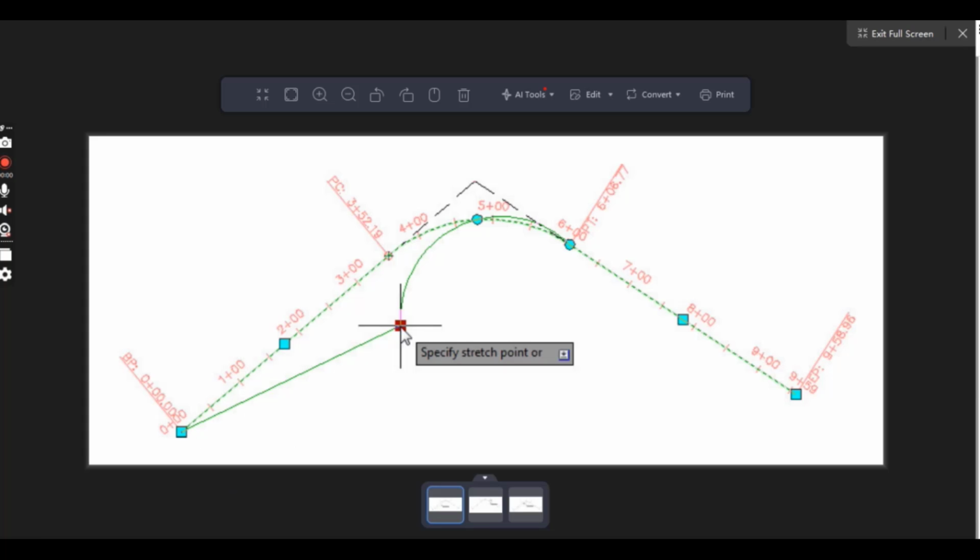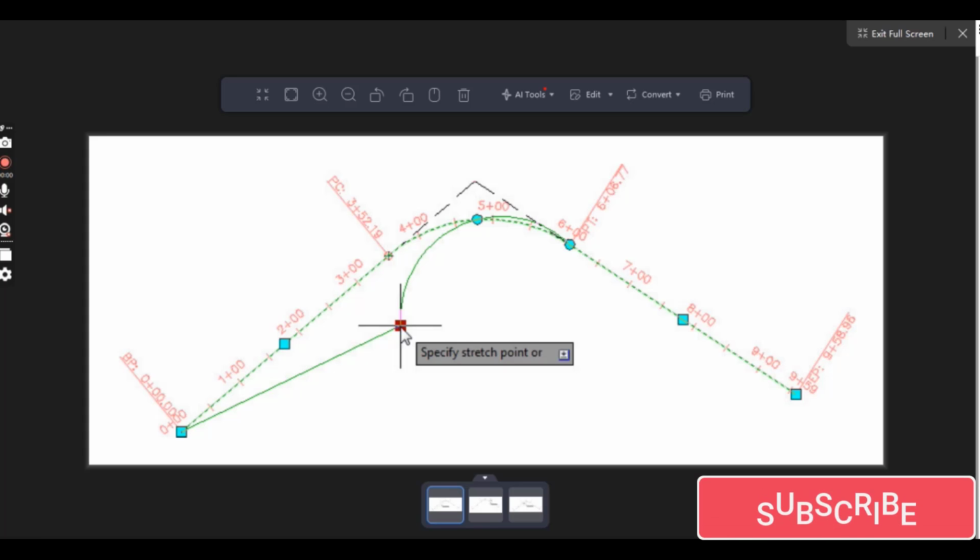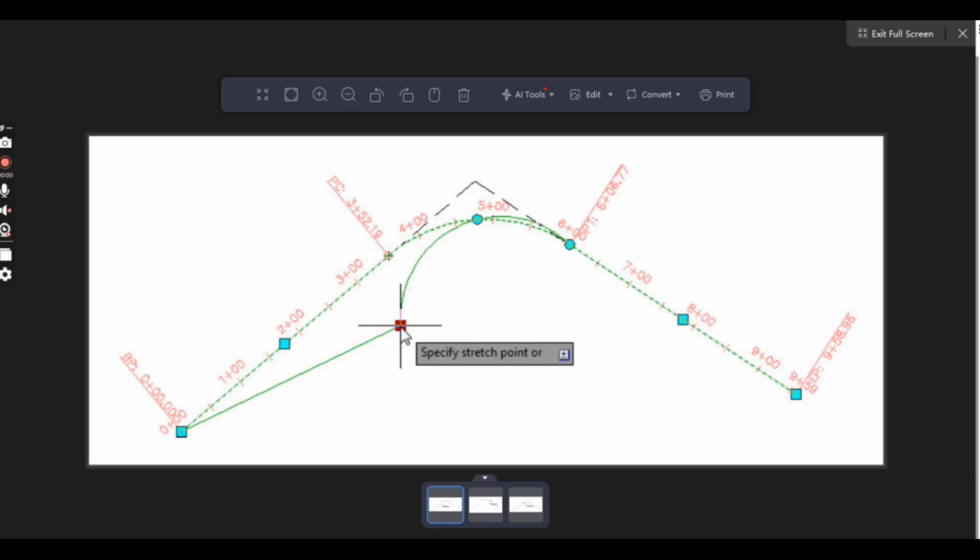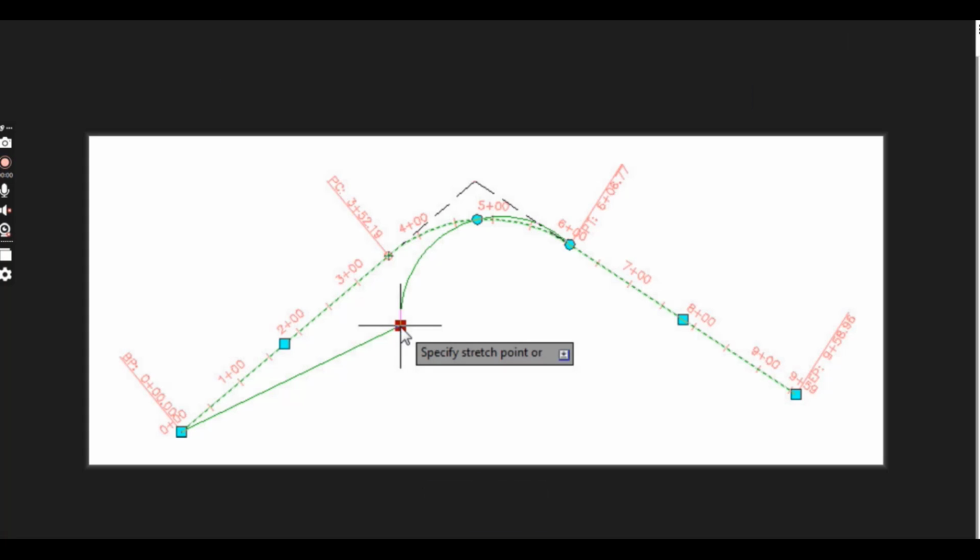They are defined by connecting points in the coordinate plane and are independent of the segments that occur either before or after them in the alignment. Fixed segments can be created as tangent to other components, as you can see in this figure, but their independence from those objects lets you move them out of tangency during editing operations.